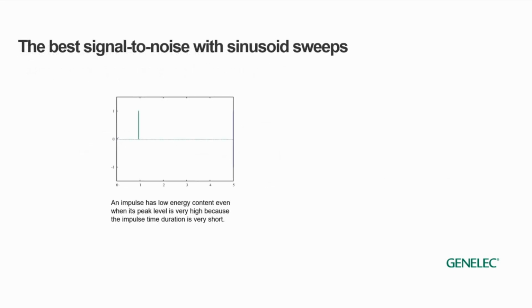There are some challenges with using pulses as signals for measurement. One of the problems here is the pulse that covers all audio frequencies has to be extremely short. In order to obtain a meaningful and reliable repeatable measurement, we would have to have sufficient energy in the signal in order to generate sufficient level in our measurement.